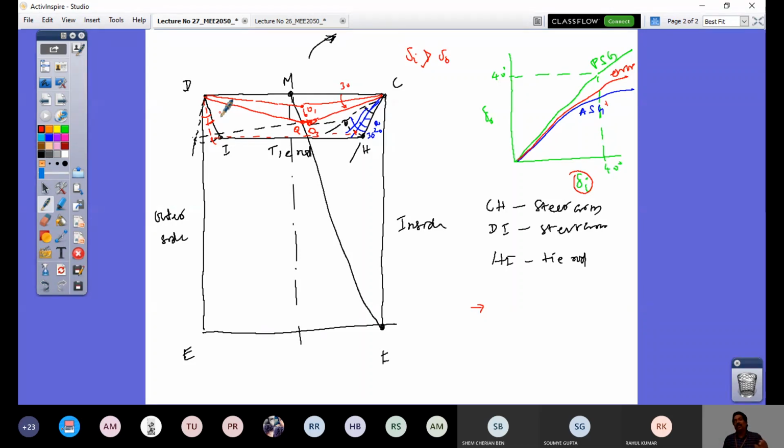So the graphical approach is simple. You could have studied in the mechanics of machines course the Freudenstein equation. If you are giving some range of input for the crank, what is the range of output that you are able to synthesize? So you are able to come out with the dimension of the connecting rod in that mechanism. The same essential kind of approach is required to synthesize your steering mechanism, right? That is what this is.